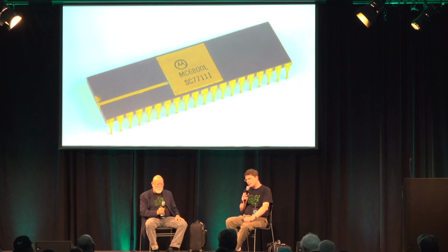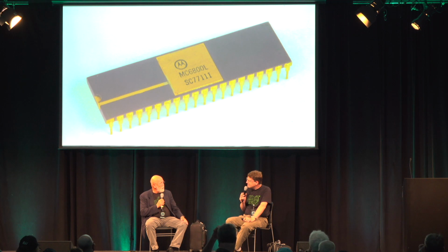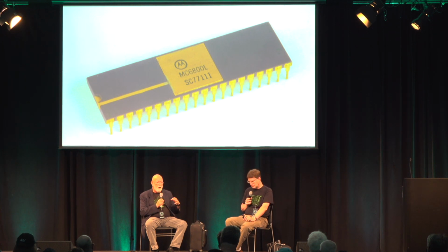Okay. And what participation did you have with the 6800? Well, I have several patents on it, but we shared patents. The circuitry, I designed the buffer system of the 6800, and all of the Motorola 6800 family of chips used my circuits. And I also designed the process control monitor that would monitor every wafer to make sure it was in spec based upon the parameters that we engineers needed to use. So they asked me, and so that was one of my responsibilities. I compared the actual in-lab test of the transistors and could extract the parameters that we'd use in our simulators.